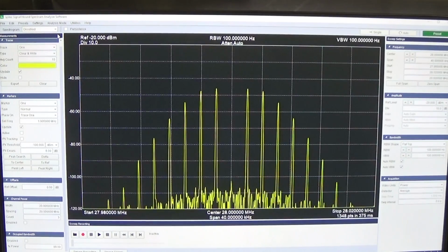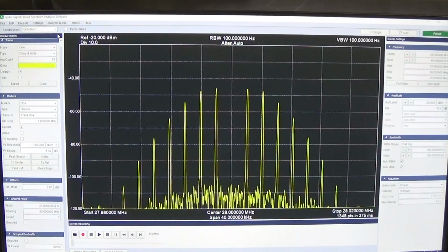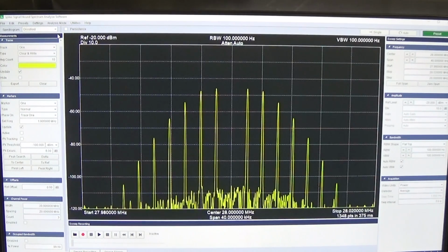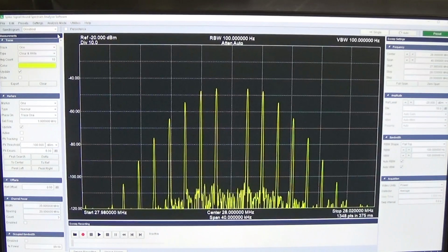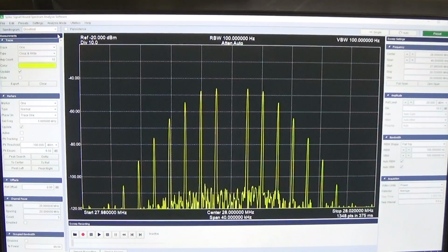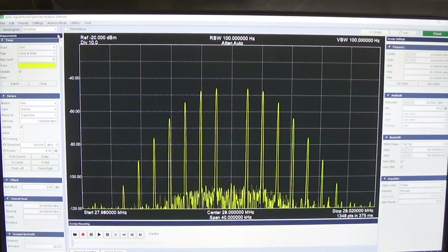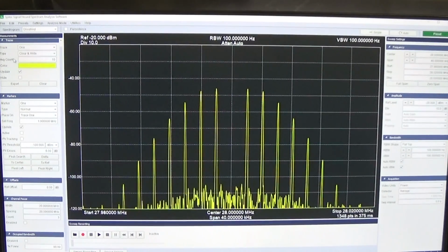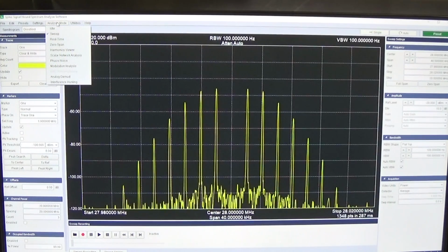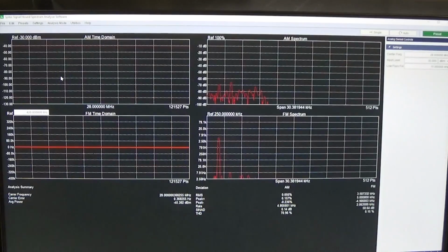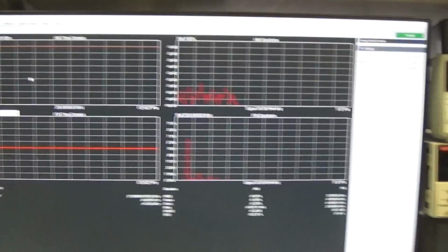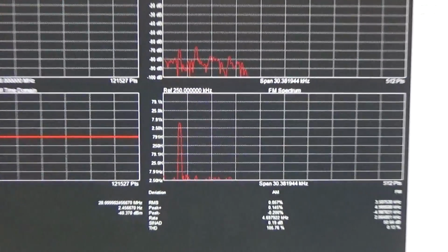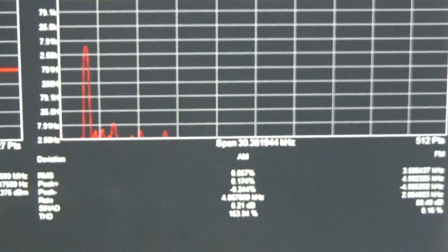Well, but maybe you cannot believe it, so maybe I have done something. But anyway, we leave everything alone now, so we do not touch any instrument. The only thing we want to do is change our spectrum analyzer into an analyzer mode. The analysis mode is up here, and I change to analog demodulation. And now we get here all the information about the signal we have.